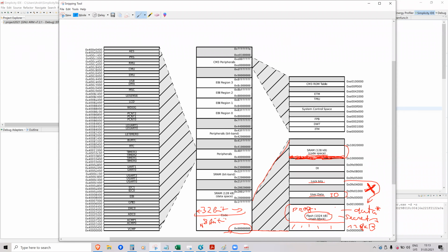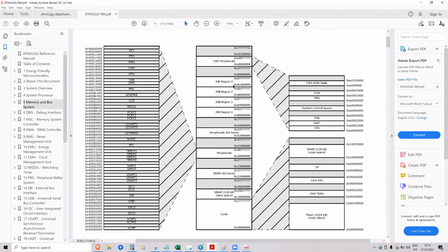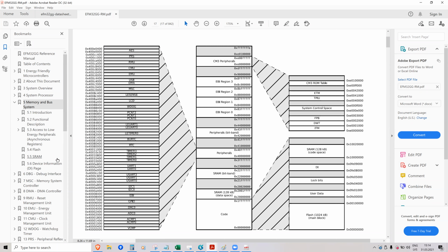And also these lock bits allow us to lock some parts of the flash memory against our own accidental overwrite. So that's pretty cool, and all microcontrollers have it. And in reality, when you work on real projects for some companies, of course, these companies want to keep their programs a secret against reading, against hackers. So you will always want to use the lock bits.